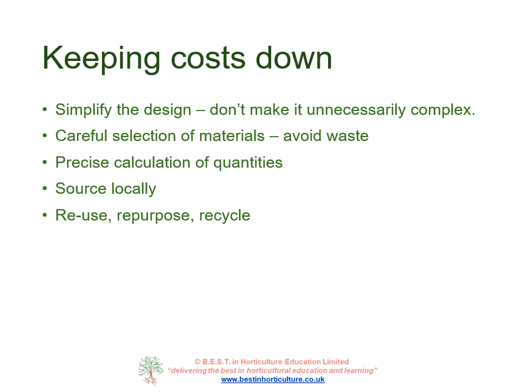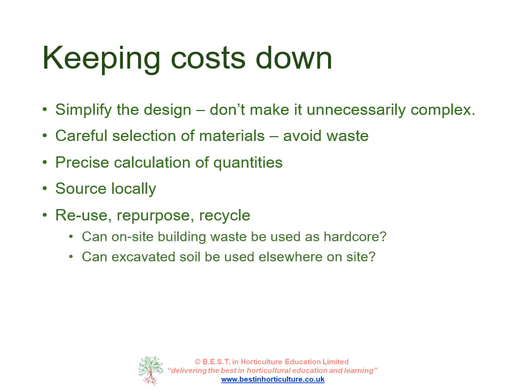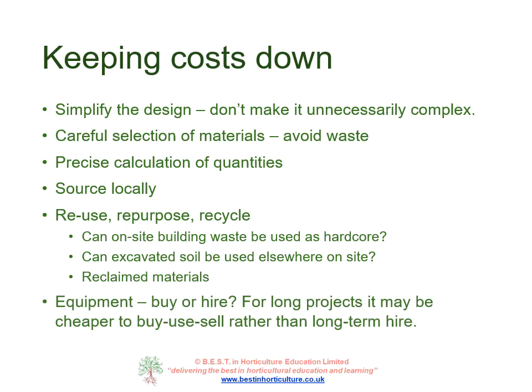Have a good look around what's already on site. If you're ripping out an existing area of paving to replace it with something else, can you make use of the building waste as a hardcore? Can excavated soil be used elsewhere on site rather than carting it away? And what reclaimed materials could we use? If we're considering equipment, we need to make a decision perhaps whether to buy or hire. If our project's going to be over the longer term, it may be cheaper to buy, use and then sell rather than put something on long-term hire.